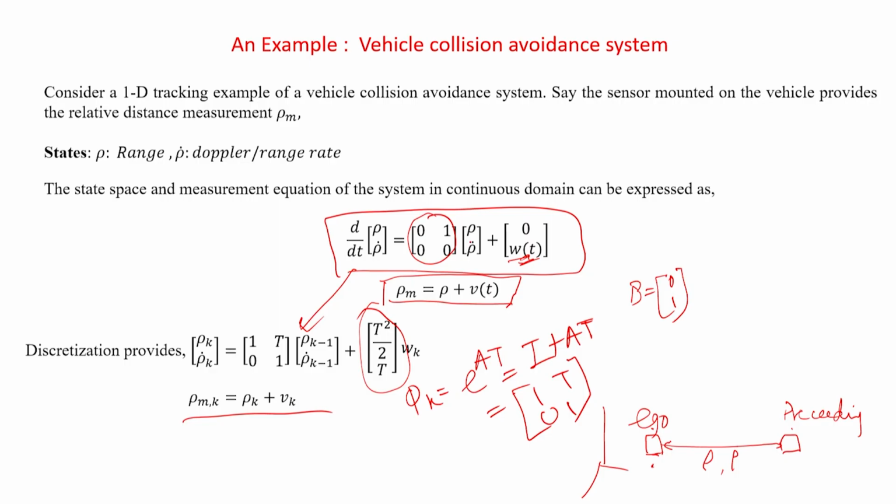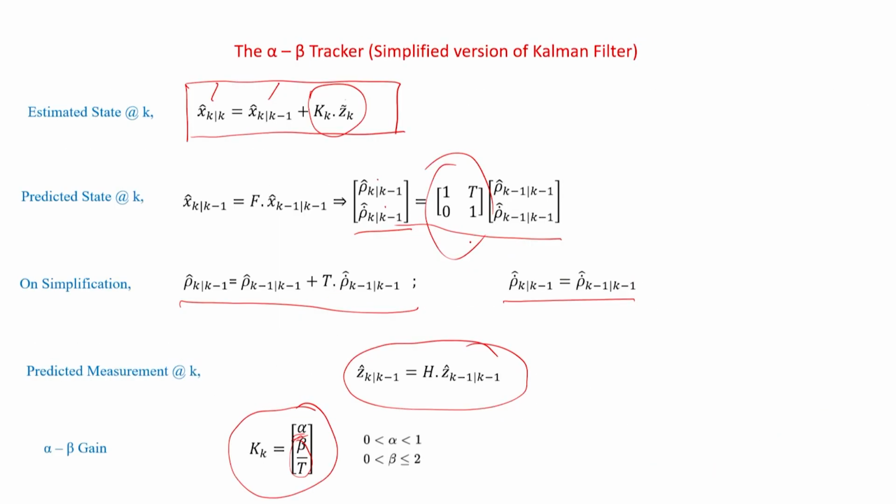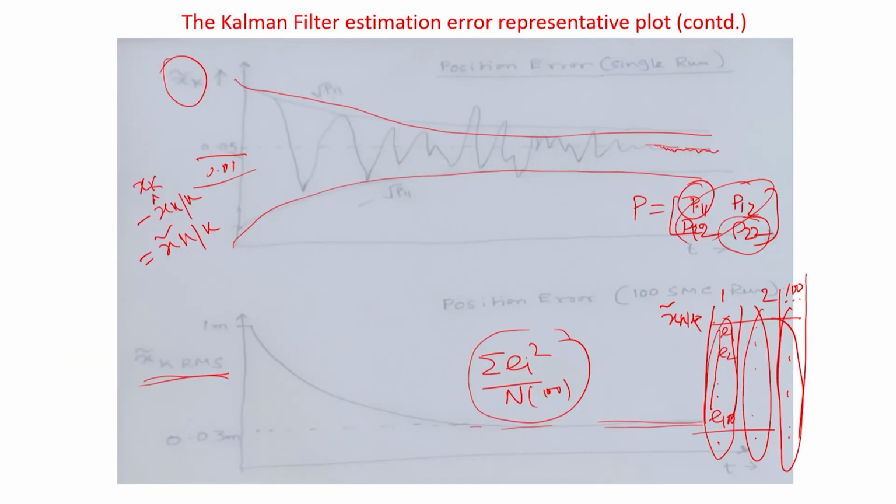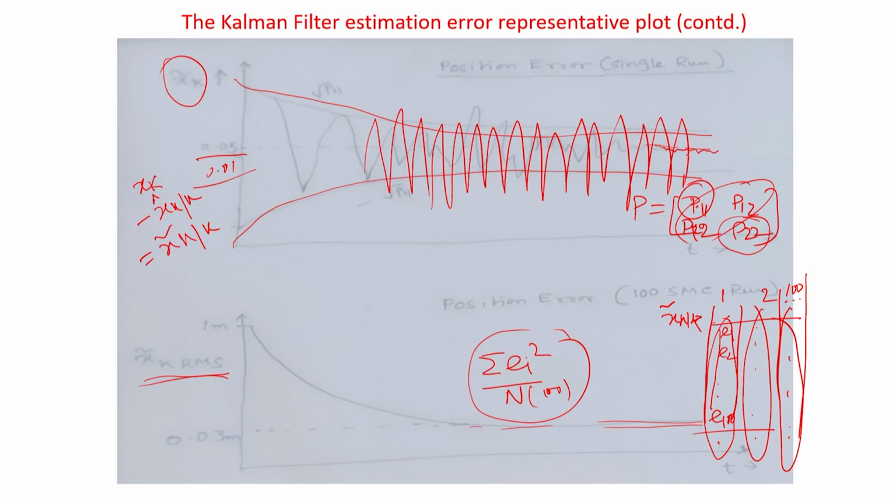Then I do not trust my constant velocity process, and if your measurements are actually simulated from a CV model, then you can definitely expect the noise to become very large. The filter will converge, I do not mind, but the noise will be much larger, unless you simulate the measurement from an accelerating or turning vehicle. If you are moving in a constant line, this is what happens. So, this is the choice of Q. You need to be very judicious about your model.